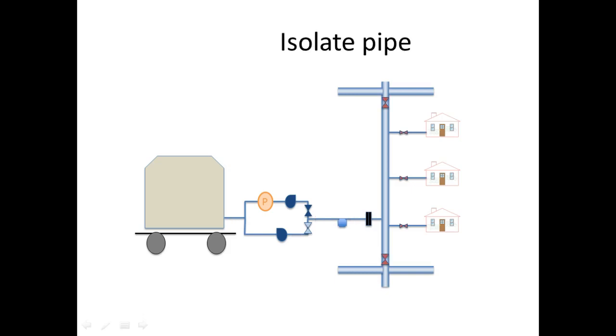We then isolate the pipe, we isolate all the users, and then isolate the valves on the main line. We would open this valve again then, because if any of the isolation valves are not sealing, we'll be able to see that there's a flow continuing to flow through that. And if we find that, we can characterize the size of that leak, and we can say which valve it is. So we're trying to get as much value from this test as we can.